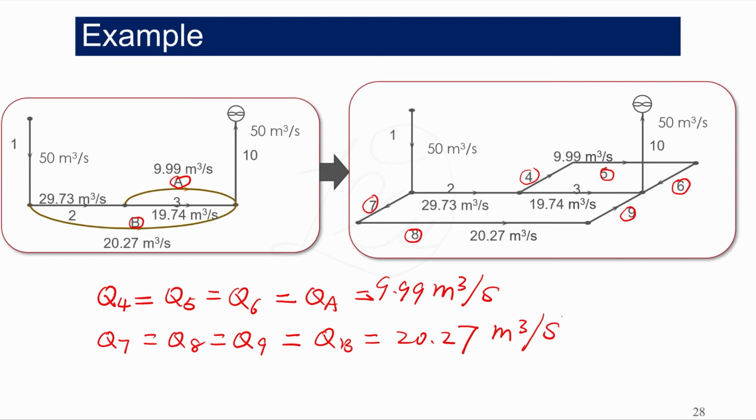So now this ventilation network is completely solved. We know the air quantity flowing in each airway. We know the resistance of each airway. We can calculate the pressure drop in the entire mine, and we can also calculate the pressure drop in each individual airway, because we know the resistance of that airway and we know the airflow quantity in the airway. And pressure drop equals RQ squared.